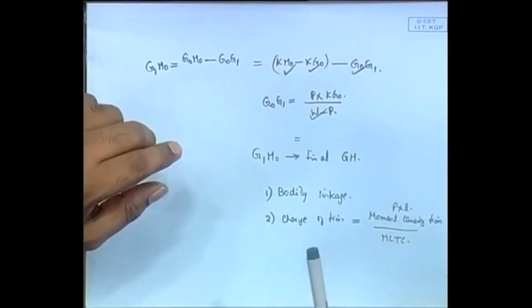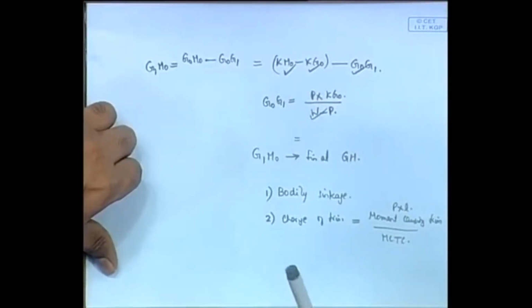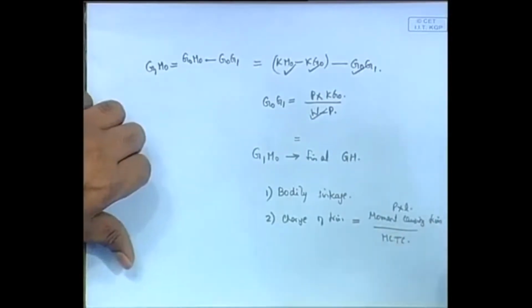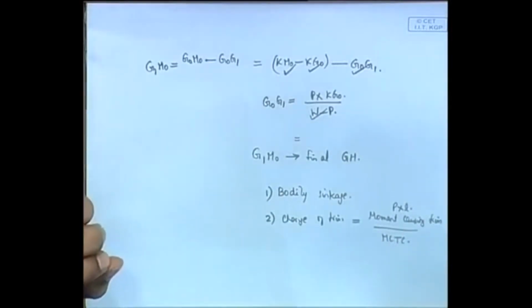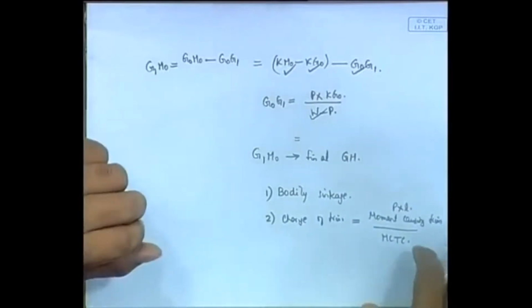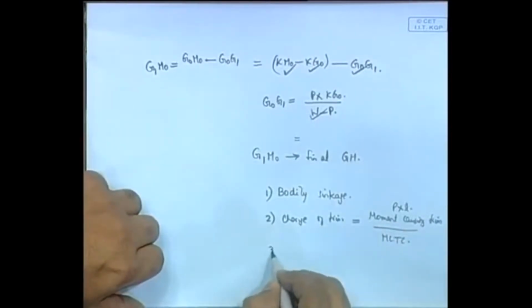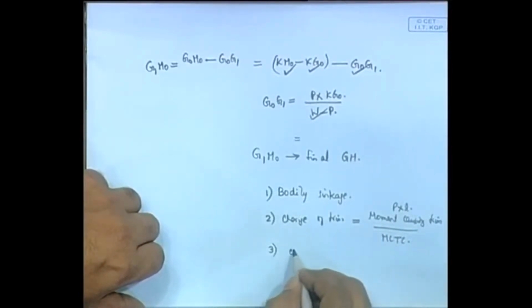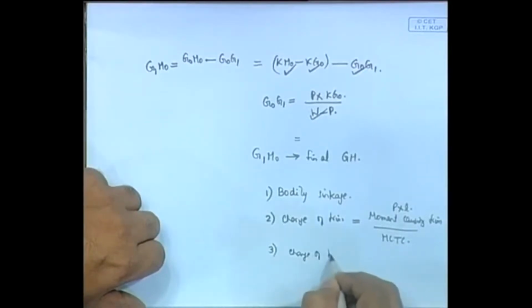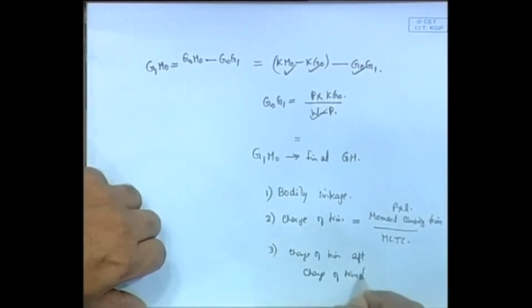When this P force comes, the reaction force from the ground comes. So, you have P into L. L is again the distance between the aft perpendicular and the center of flotation. So, you find the change of trim, and then once you find the change of trim, you find the change of trim aft, and the change of trim forward. So, you find these 2 things. Now, aft is given by small l by capital L into total T, like that.